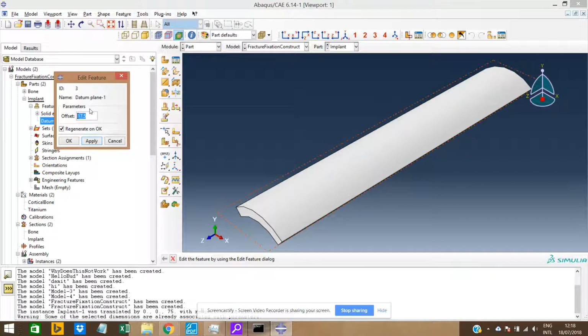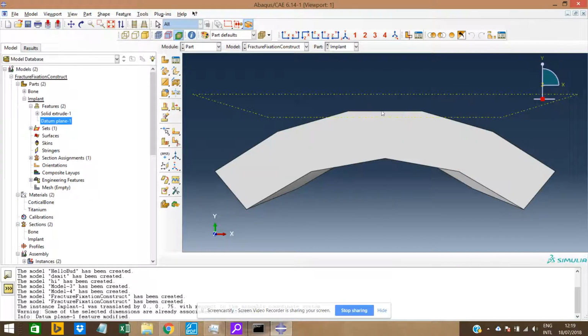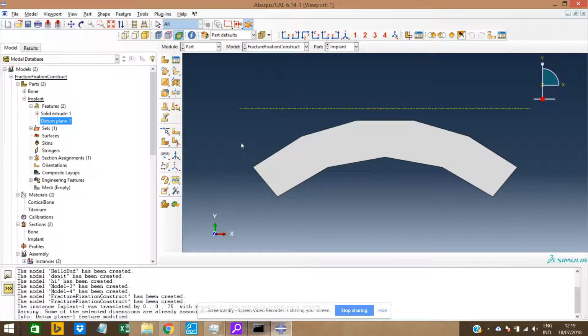so I'm gonna actually want it to be over the top surface of the plate, which, as you remember, was a 21 point. I want it to be a little higher. I want it to be at 22.5 such that it's 1 millimeter. It looks a bit more like real screws, right? It's 1 millimeter above the top surface of the implant, the plate. And now I'm gonna go and make some extrude. Before I did a cut, now I want to just make these parts, right? Extrude a few circles that are gonna be my screws.